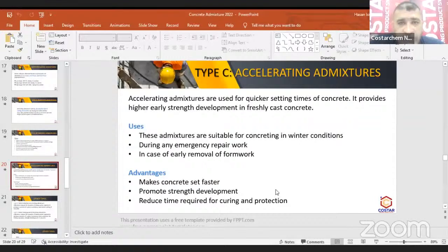If you use type C admixture to accelerate, type F admixture, which is just like water without retardation, and type G admixture, which is a superplasticizer, and let's say the three of them reduce the water-cement ratio to the same level. Type C will give you an early strength. However, it will give you a modest final strength. You'll achieve it, don't worry, we can work on it, but it will be modest.